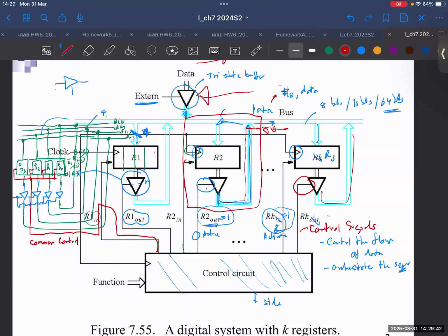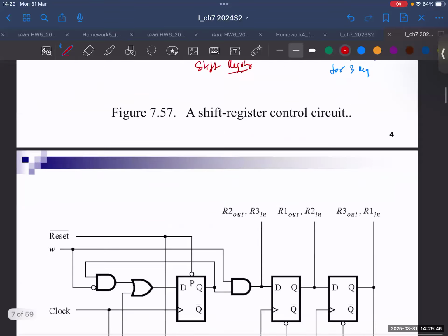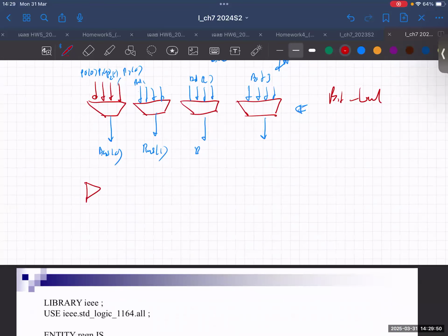Pretty much. Do you remember that for outputs, you cannot connect them together, right? For example, like this. If you connected the outputs together directly, what happened? If there's a conflict between the outputs of each one, then one gate will be destroyed for sure.